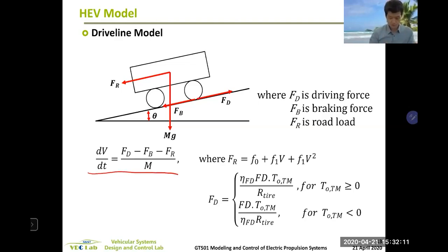So it's F equal ma, where F consists of driving force, braking force, and then resistance. Okay, and resistance has three terms, right? And this is driving force, which is coming from the powertrain. And then we have brake, right?